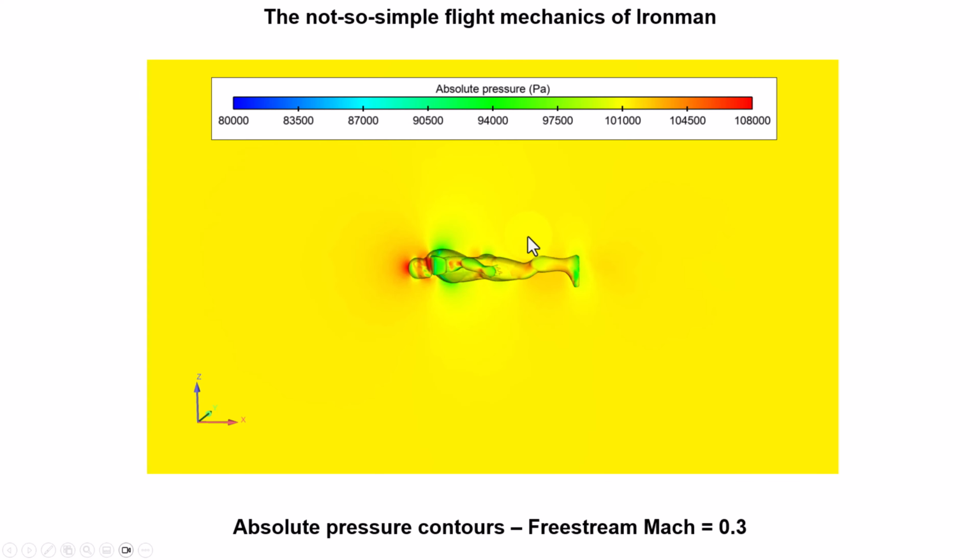Then, well, some pretty colors now, this colorful fluid dynamics. Here we have now the pressure contours. I'm mentioning that the next step will be to balance this, so I will run another campaign of simulations. Also, if somebody wants to help me, let me know. I'm sharing all the data. My next step is going to be overset meshes. So I will have that condition, and in overset meshes, I will just paint on the surfaces of Ironman some patches where I'm going to inject some moment just to keep it aloft.